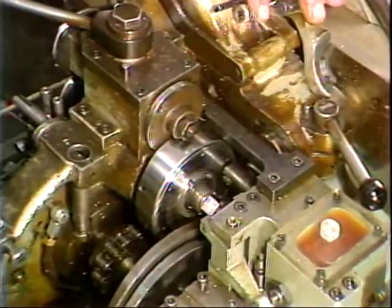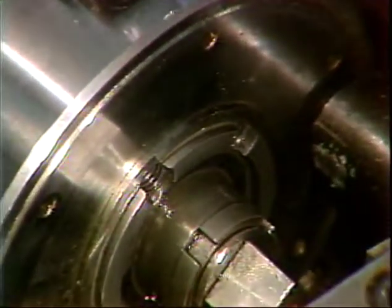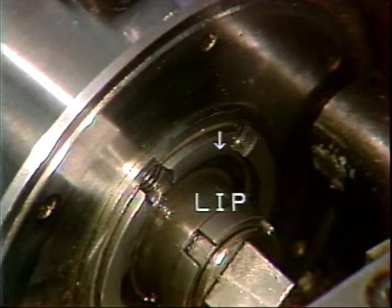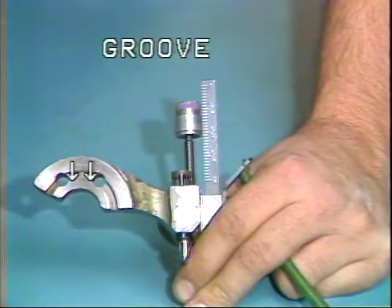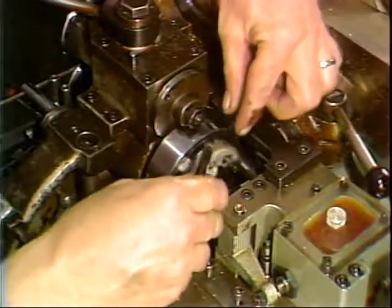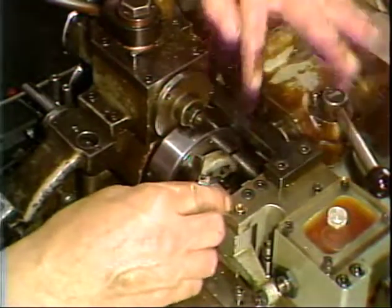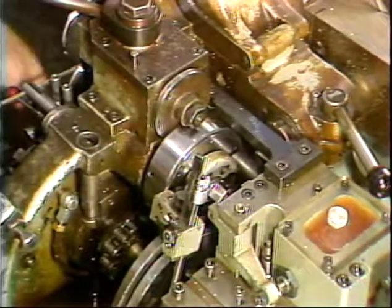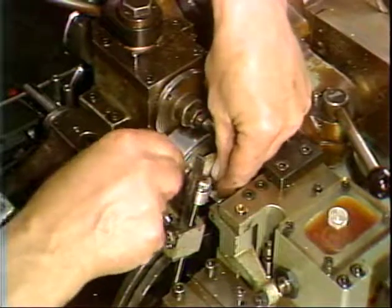The 2-to-1 feed attachment is mounted here to the friction clutch. This lip on the friction clutch must be aligned with this groove on the back of the 2-to-1 ratio feed attachment. Place the feed attachment into position and align the holes for the 2 mounting bolts. Install the 2 mounting bolts.